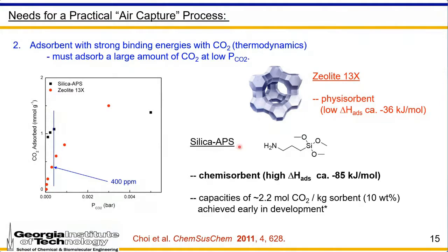Furthermore, if you remember your organic chemistry, amine CO2 chemistry is operable in all ranges of humidity, and water doesn't compete with CO2 in most cases for adsorption on these types of sites. In contrast, we know that 13X will swamp out the CO2 with water when water is present in large amounts.